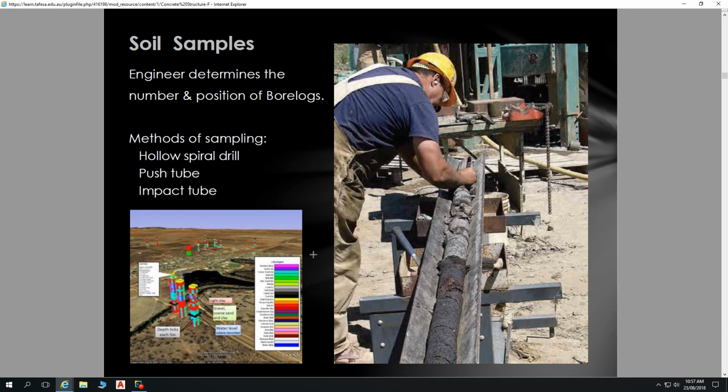So soil samples. So here's our hollow core. That's our sample of soil. Now this might be a very dry piece, and that might be fresh come out. That's the way it looks to me. But whenever you take a sample of soil down, essentially you're going through time. In some instances, you're going through time, through various different layers of soil. So soil can be deposited in certain sections through various different events over time, and you get these different horizons of soil happening.